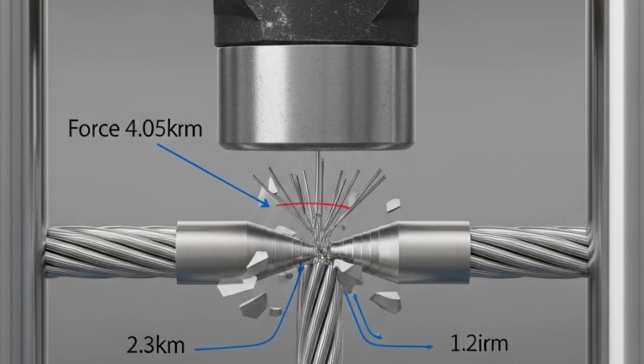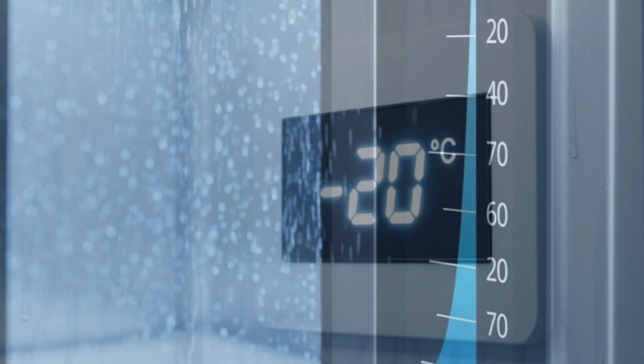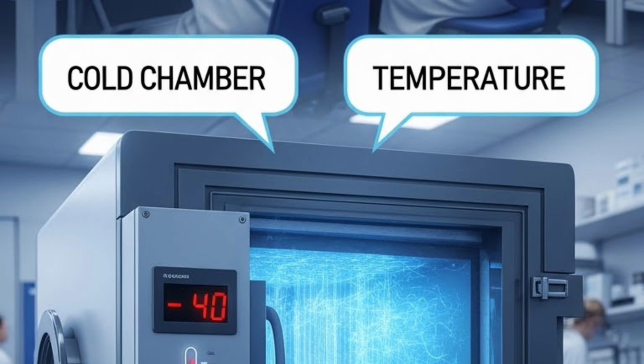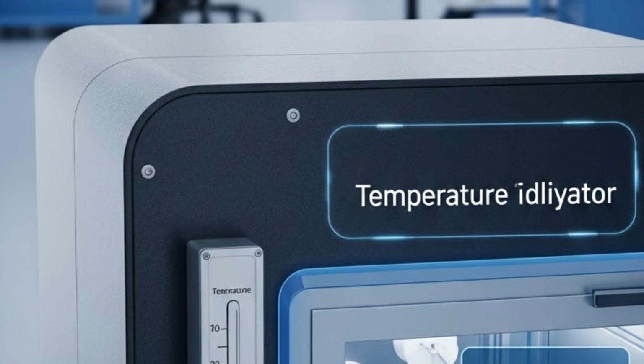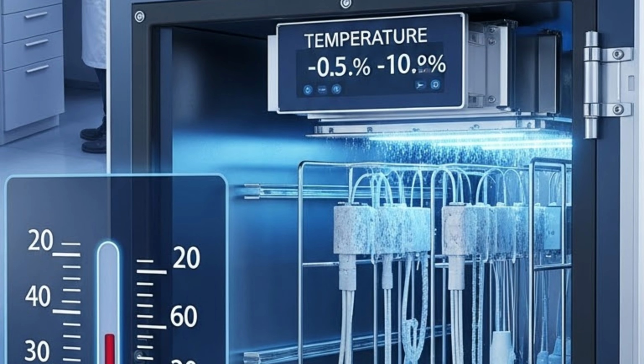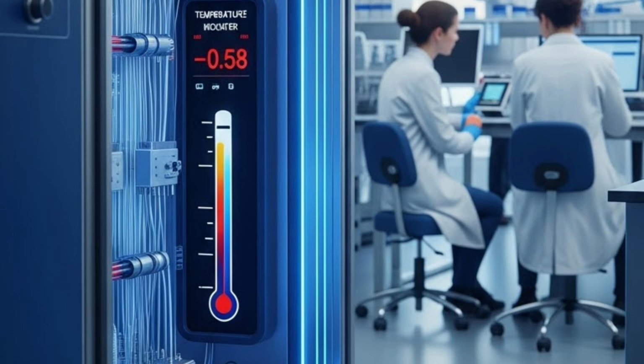Low temperature conditioning. The cable samples and the apparatus are placed inside a low temperature cabinet. They must be kept at the specified temperature for at least 16 hours. This ensures the sample reaches uniform cold temperature.